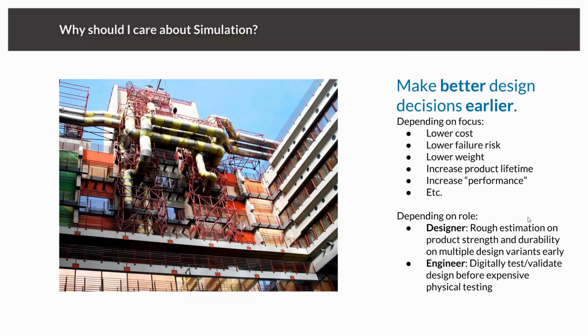And why I'm telling you this, because in the end of the day, simulation allows you to find a better design at an earlier stage, and that's why you should care about simulation. It depends on your perspective and on your focus, but you can use CFD to decrease costs by saving physical prototyping. You can use CFD also to reduce the failure risk by, for example, validating experimental testing or assumptions. You can use it to optimize the performance of your part by testing different design approaches, for example, to reduce the pressure loss inside the ducting system, and so on and so on.